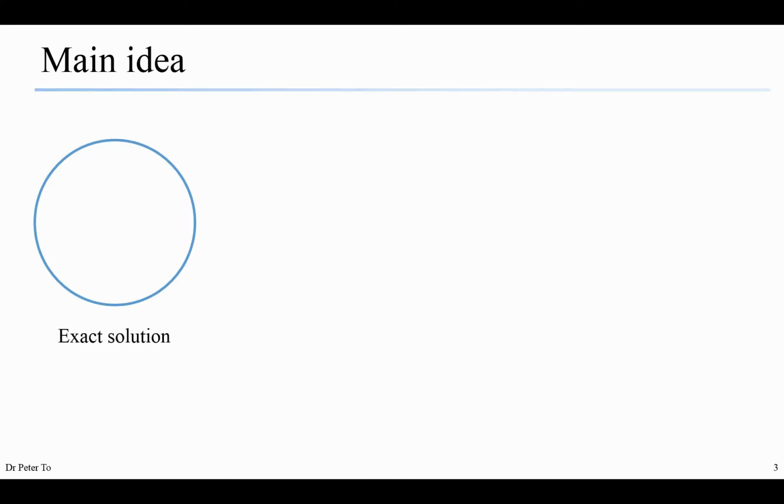Now we try to analyze the other five of six steps of preparation. In the first step, symmetry is used to reduce the computational cost. For example, if you have a symmetric temple like this, you can just cut it by half and simulate the reactions, the interactions between two parts, by the roller support.